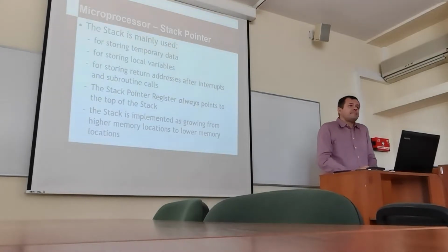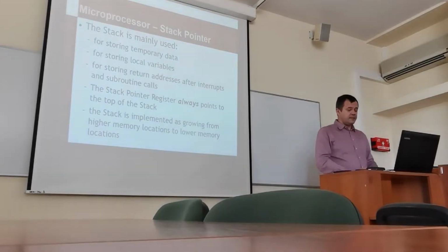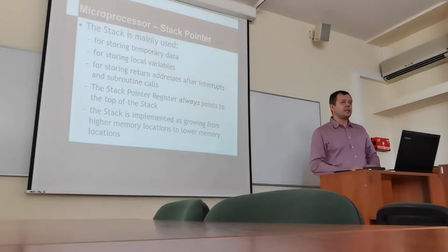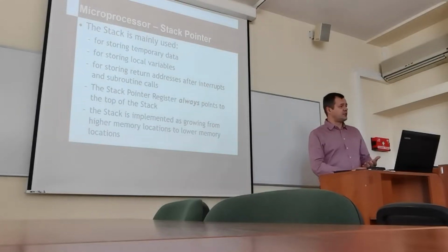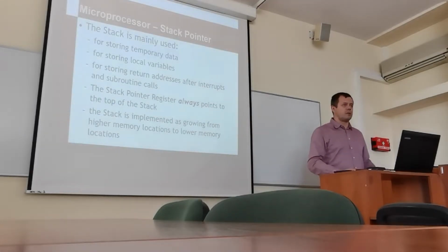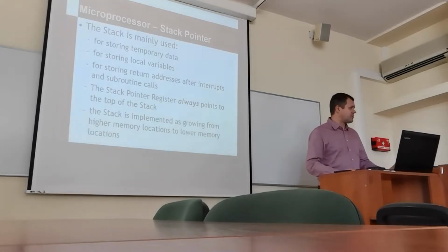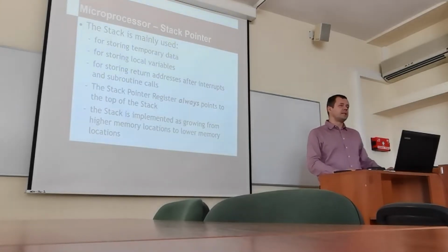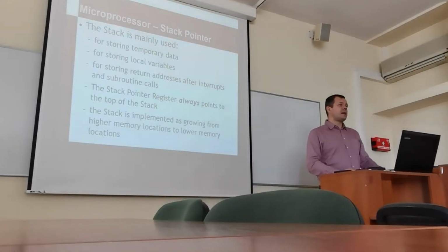What is a stack? Stack is, as the name suggests, a structure which is last in, first out. So the structure which is called LIFO structure. Last in, first out. But the LIFO structure here is usually hardware supported. Hardware supported means that we don't need to do it in software, but this LIFO structure is supported directly by the instruction inside the code. Which means that first of all we've got special instructions. I will show you the instructions next week. Special instructions for placing data onto the stack and getting data back from the stack,